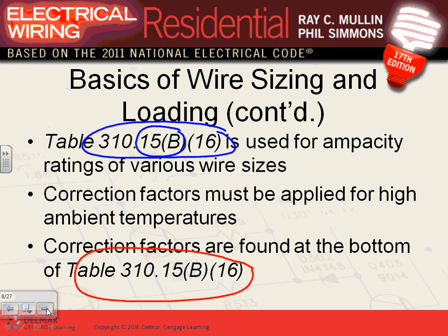That's what we're going to be doing in residential, and it's not a big deal. But when we go commercial industrial, derating becomes a big deal, guys, because bundling means saving money. If I have a 3/4 inch conduit carrying 12 conductors, number 12, on a 3-phase system at 277 volts, I can feed close to 300 lights. Remember, the voltage is high. We will do this in commercial, so bundling becomes a big deal when it comes to commercial industrial. But we will touch on the derating factor and how to do it.